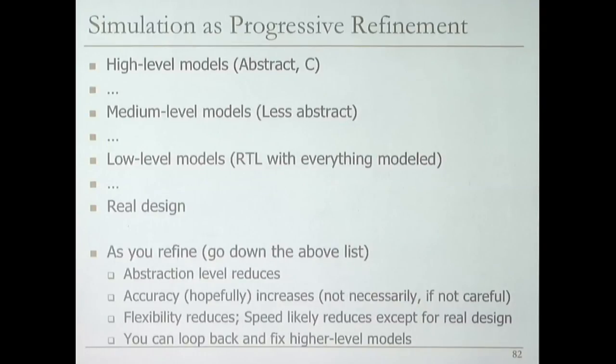I have one more point to make over here. Even if you have an RTL design that models everything, that's not the same thing as the real design, because there's stuff that goes on in between the RTL and the real design. You lay it out, and it turns out there is an error between these two things, because you don't necessarily model everything in the RTL. Later, the VLSI circuit designer who does the design changes some stuff that doesn't get propagated back into the RTL.